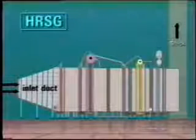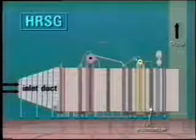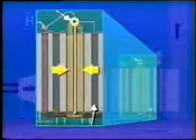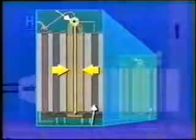Here we have the IP economizer feeding water into the IP drum. Here is the IP downcomer, the lower headers, and the IP steam generation tubes or risers. Steam from the IP drum is fed into the superheater, finally exhausting for intermediate pressure usage.